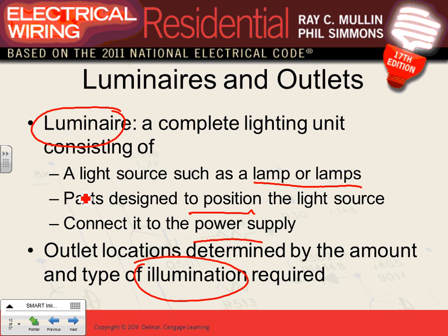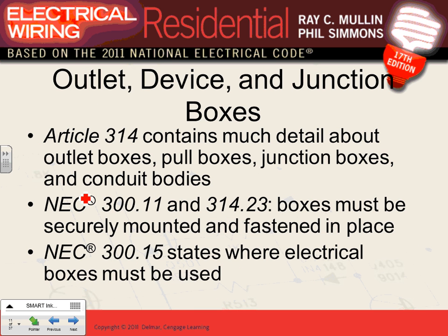Now, you're going to see, we're going to go a little bit more than the minimum. We're going to put cans to make things look good. We're going to put fans and so forth. But typically, to meet code, all you need is one in every habitable area. You're going to put a wall-mounted switch light in certain applications, or even a fixture switch light in other applications. Any comments, guys, about luminaires that you're going to be using? Luminaires. That's a couple of things.